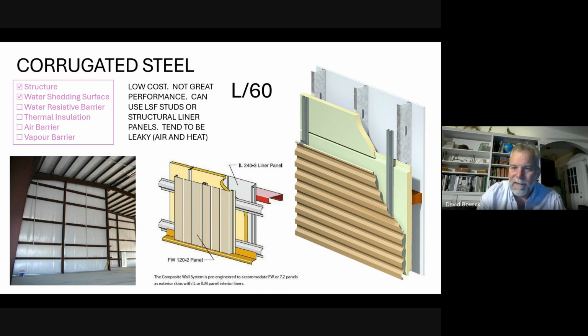So you can see what these wall assemblies look like. The one on the right is our commercial wall assembly, where we have studs, sheathing, which isn't represented, insulation on the outside, and hat channels. A hat channel is hat shaped, which is why we call it a hat channel. It gets screwed to the outside of the insulation through to the backup stud to give you something to screw the corrugated metal to, and to create the drained cavity behind it.